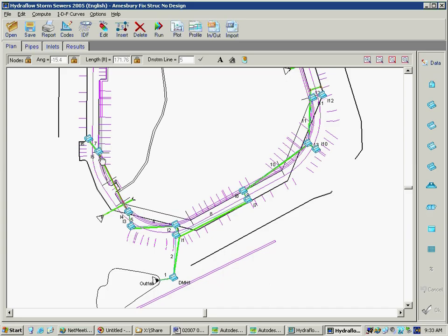This computer has double-click issues because whenever you're recording something, the double-click gets goofy on you. But if you double-click the pipe, it will open up this dialog. The point I'd like to make is to lock that stuff. If they're not locked, it's very easy to change this angle. You double click it and your whole thing rotates off base, and it's like, whoa, what just happened there?